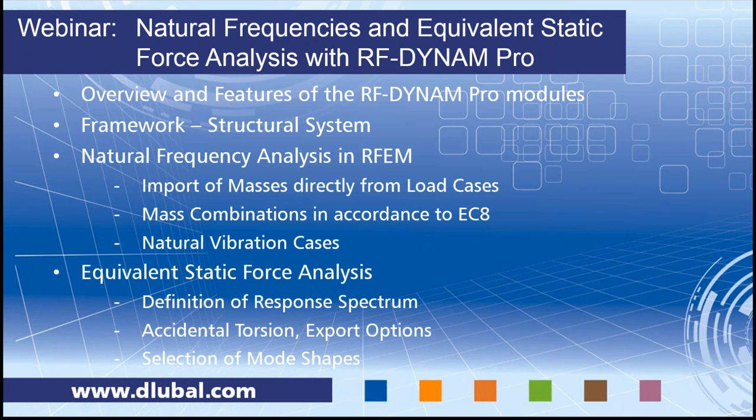We will perform an equivalent static force analysis. We will define response spectra in accordance to Eurocode 8. We will apply accidental torsion. We will use the export options available, and we will use a new feature which is the selection of mode shapes. So we get started.